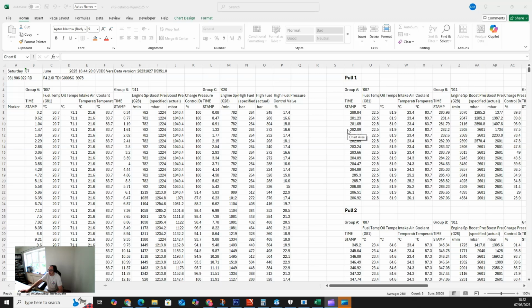My approach when doing this is, if you want to think of it this way, how can I replicate a dyno run on the road or as close to as possible? So I want to bring the engine down to a low speed, so kind of like 1500, 2000 RPM ideally. And I want to basically match the throttle, so I put the engine under 100% load and bring it up to the red line or as close as possible.